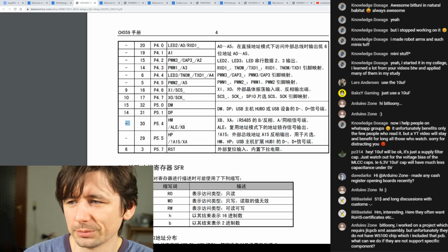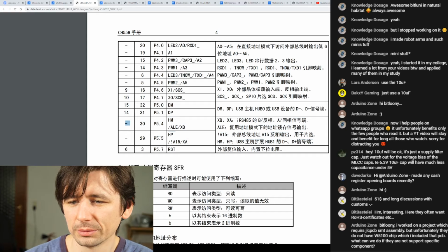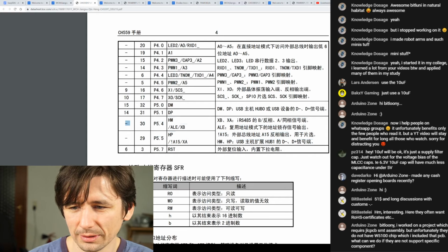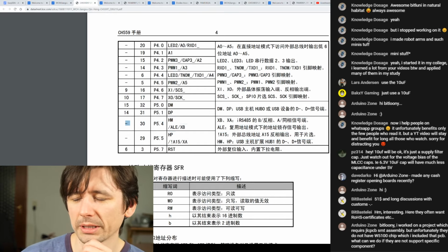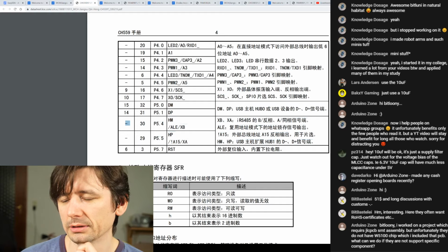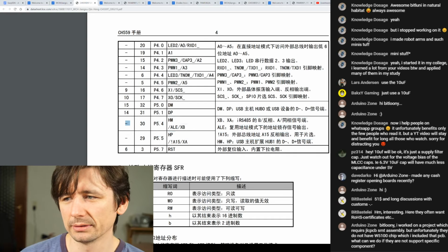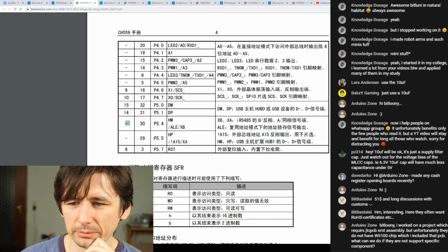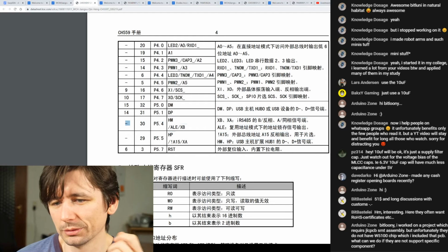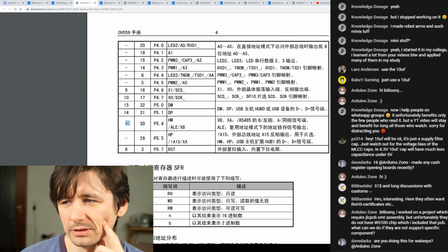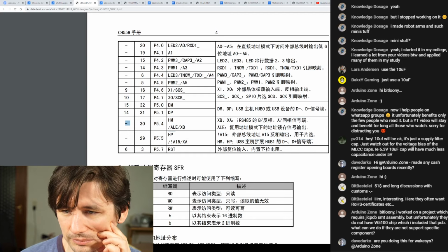So Arduino Zone, do it somewhere else. You can simply not place the part and do it by yourself if you want to do that. I'm talking about Arduino Zone. So what I did with my camera programmer, they didn't support USB connectors. So I ordered without the USB connectors and soldered the connectors with hot air here in my lab. And that's what you could do if you want to do PCB assembly at JLC, or use another assembly service for that.